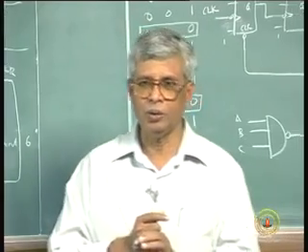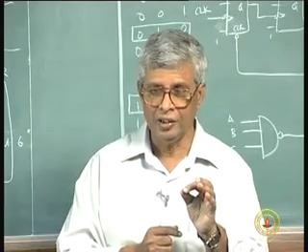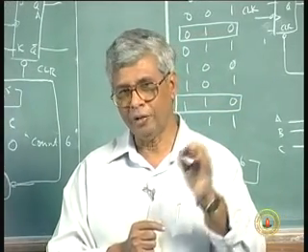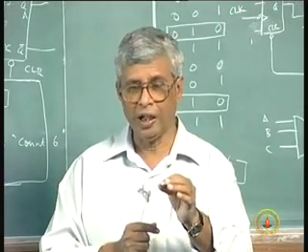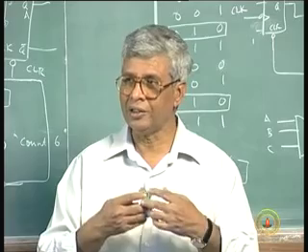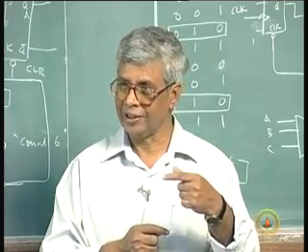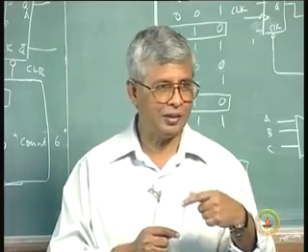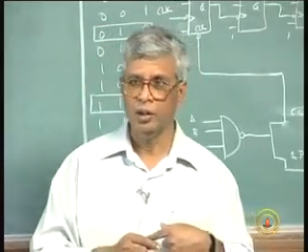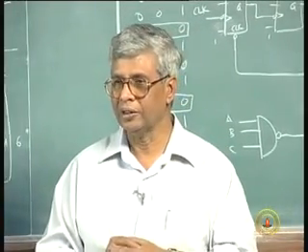So the crystal frequency clock has to be brought down, the other way, from very, very high. You do several divisions to make it one cycle per second to count seconds, then divide by 60, you get 1 cycle per minute, divide by 60 again to make it 1 hour.